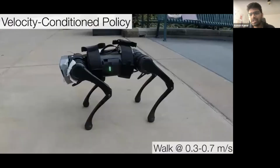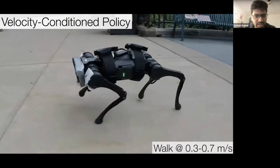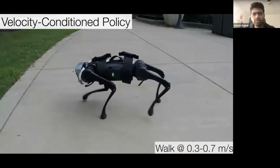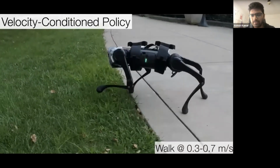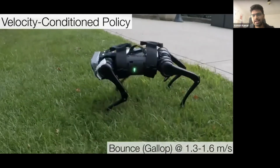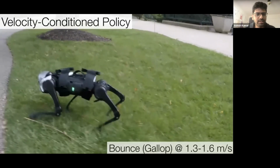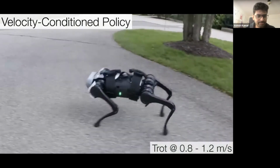Now that we have 3 policies which can walk at 3 different gaits, we can also distill them into one policy using supervised learning. So we have a supervisor or a teacher which knows how to walk in each of the 3 different speeds, and we can distill that into a single policy. And we can get this kind of behavior where now we have a policy, and all we need to do is give it a target velocity, and then it walks at that. It automatically switches to the right gait, figures out what the right gait is, and continues walking.